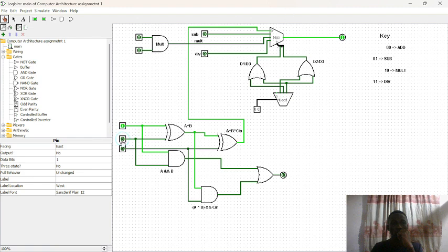But as soon as we add another 1, it now is equal to the base, so we get a 1 and a 0. The 0 is what is going out here. Because it's a 0, this gate is off now, so you won't see an output, but you will see a 0 here telling you that it's 0. But the carry, which is a 1, is being displayed here. So this is how a basic addition is done here.